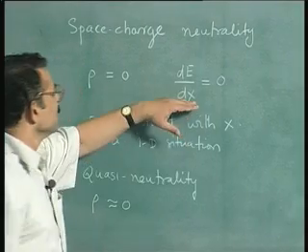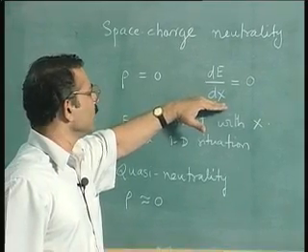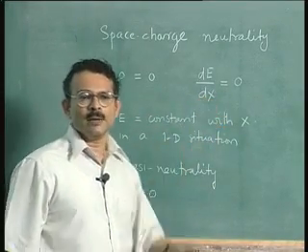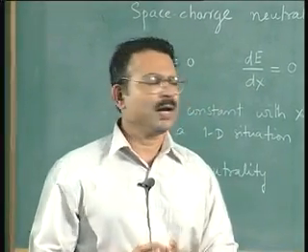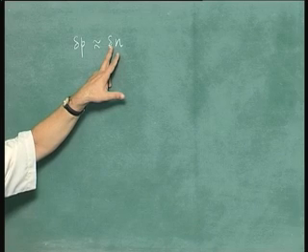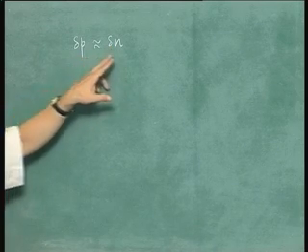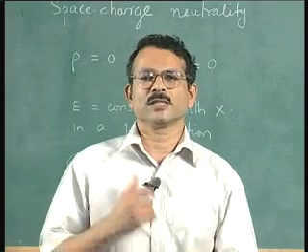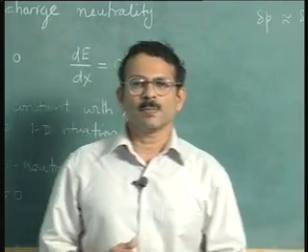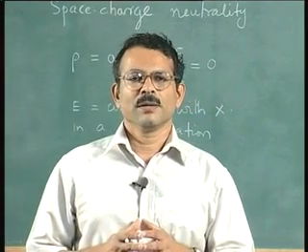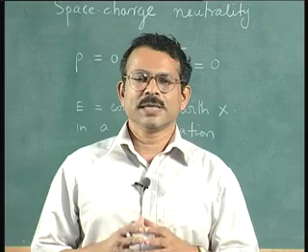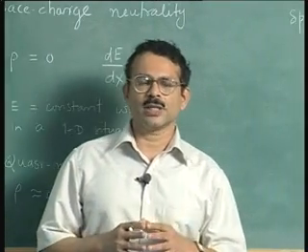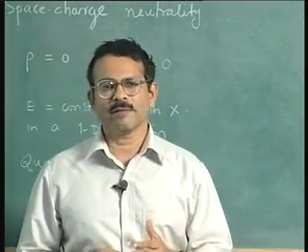So noting the fact that the Gauss's law is also simplified under the neutrality or quasi neutrality condition, that is, we don't have to solve this equation at all, the Gauss's law equation at all. We have removed the Gauss's law equation, that is one equation out of the 5, and further, since delta p is equal to delta n approximately, we can either solve for holes or electrons, which means we need not solve for hole continuity equation and hole transport equation and electron continuity equation and electron transport equation. Instead, we could solve any one pair of equations. So the quasi neutrality condition reduces the complexity of the problem, since we only need to solve for only 2 equations out of the 5, any pair of equations either for holes or for electrons. By pair I mean the transport equation and the continuity equation.